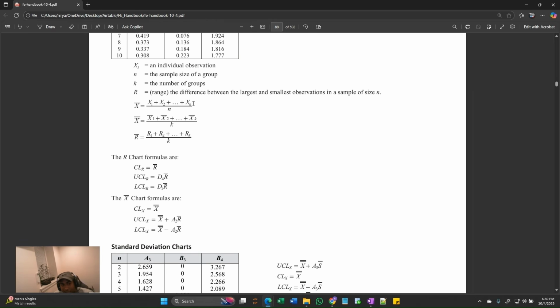They define a mean for an individual data point. That's just the sum of all the measurements divided by the number of measurements. So that would be 10 for our case. Or you can take the average of each day, that's X bar 1, X bar 2, all the way up to 7 days for our case, and divide by 7. And that'll give you the overall average of the data set. That's what we have. We also were given R bar in terms of the MMC condition. That's just the average range of the entire data set.